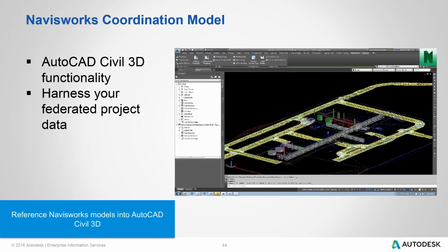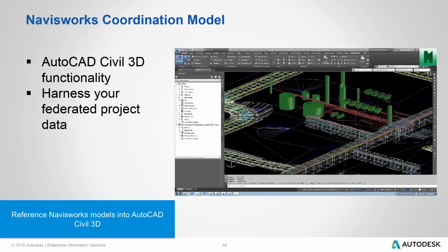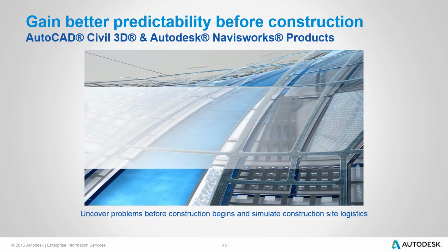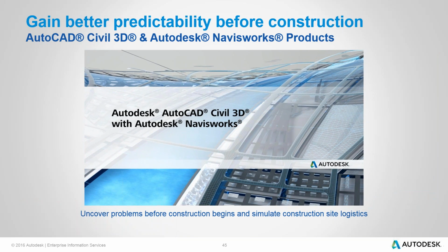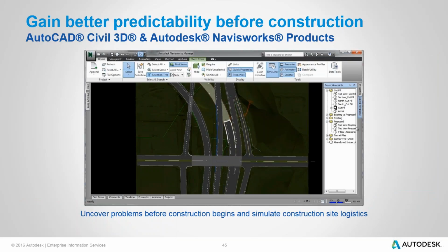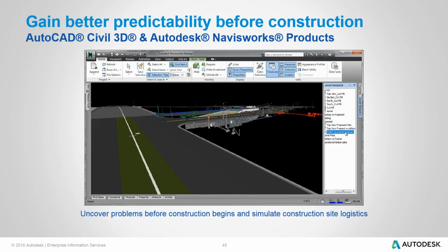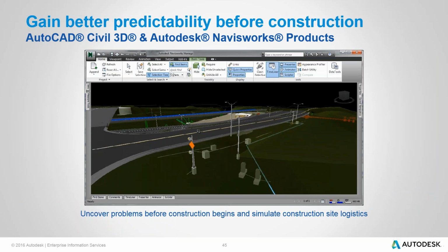You may be working on a plant site or a mine site or a hospital refurb, and you can pull all of that data in from Revit structure files, from the 60+ file types that Navisworks can read. It's a great way to just ensure that your design is in context. Utilising the 3D models produced in design, teams can identify and resolve issues virtually before breaking ground by visualising projects holistically, modelling constructability, and performing clash detection.